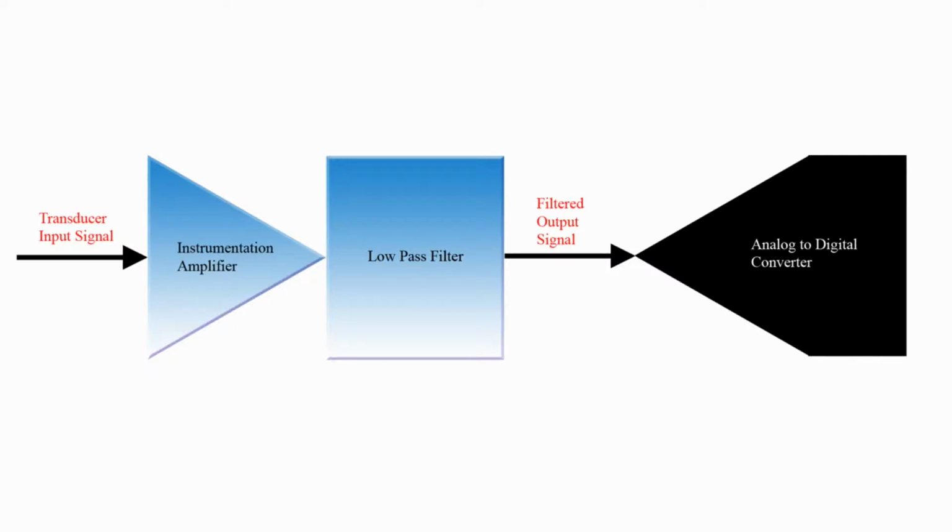Nyquist theory dictates that a digitally sampled signal must be bandwidth limited before it is acquired. Yes, you can connect your sensor directly to an ADC, but the result will include extra junk that may represent as alias or ghost signals that can move around the frequency band in odd directions. Excessive noise, and worse, it is impossible to remove these artifacts with digital post-processing.